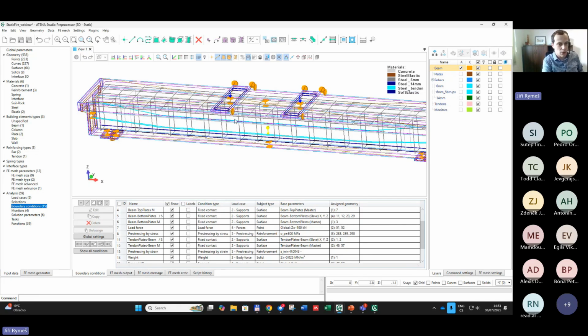One thing which may be useful is that at the beginning I assign very soft material to these load plates, and the reason is that I don't want them to strengthen or constrain my concrete material during the fire. And just after the fire, I exchange the material in these load plates to have realistic steel plates during the overloading of the model.